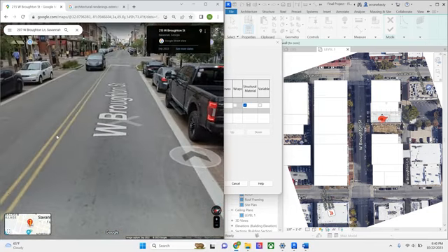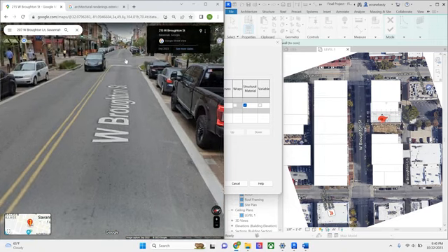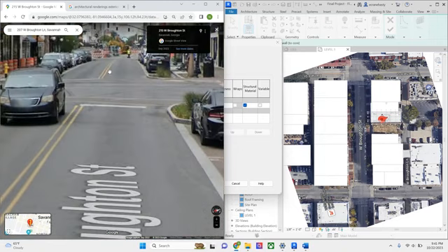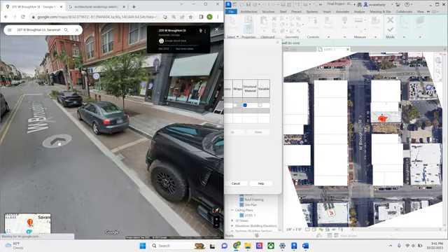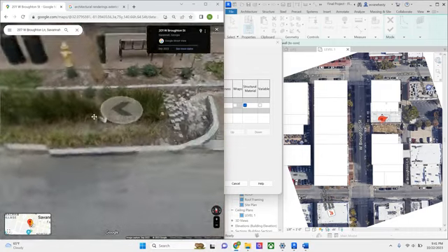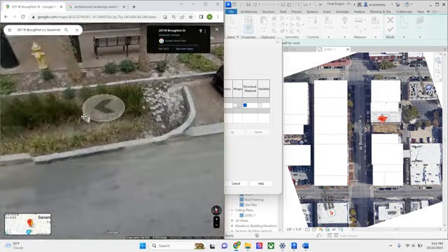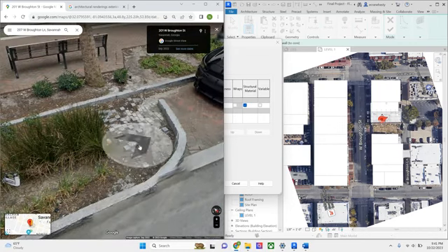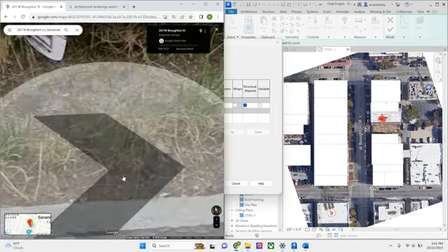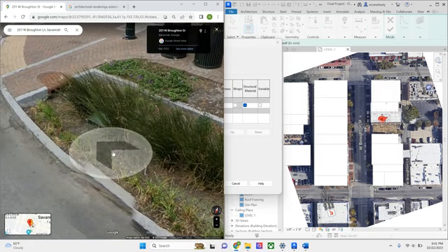And the way the street works is that this center line here is the high point. You can see it a little bit more over here. So this is the high point, and your water drains over and hits that curb and then goes to a drain. If I saw any drains over here, I would show you. There might be one. Okay, so actually what they've done, they're draining the water into this greenery space. And then I was wondering if they had any more drainage. Oh, there it is. So when it starts to pool, basically what they're trying to do is soak up all of that dirty water.